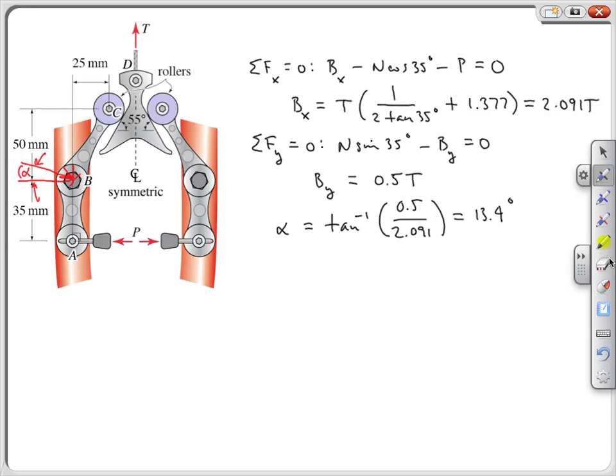Our present 2D analysis has given us the forces on ABC as multiples of T. We will see in Chapter 8 that internal loads, forces, and moments develop in these bodies as a result of such loads. If these are the loads responsible for failure, we should look for failure related to what we're going to call bending moments, although that's a term that may not be familiar to you yet, at certain locations related to peak bending moments.